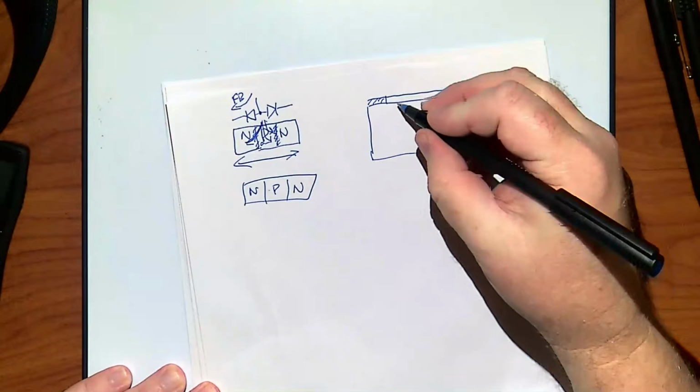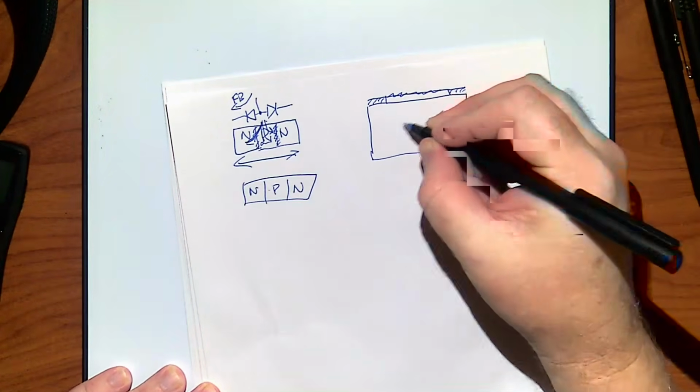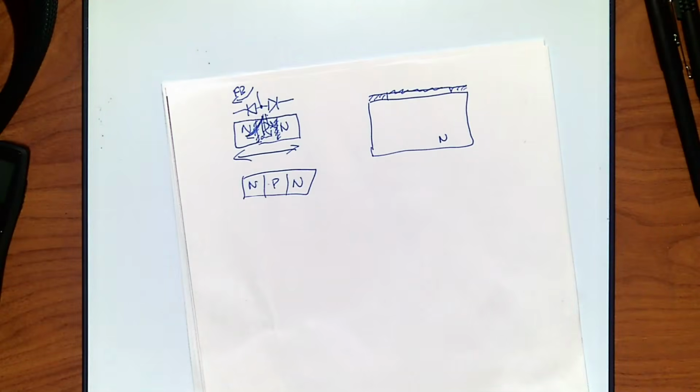So let's say I wash away this middle zone. Now this is protected, and this part in the middle, there's no longer anything there. So there's no problem, I can expose things. Now I could, for instance, do CVD or some other type of process where I expose it to P dopant in the air, with pressure and time, let it go, and it diffuses.